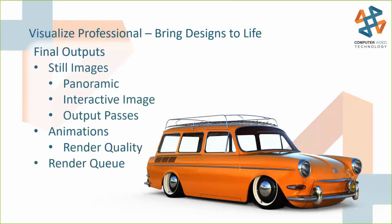So again, final outputs: we can create interactive images, and output passes for each image. If you wanted to show just the shadow or just the reflection pass, you can do that in those output passes with Visualize Pro. Of course, we can do interactive images. I don't have an example of that today, but that's also an option for export. And then full quality options on the animations for the output. And then don't forget the render queue. You can queue all of this stuff up so that you're not wasting any time watching the computer render. You can let this do the rendering after hours once you leave for the day.